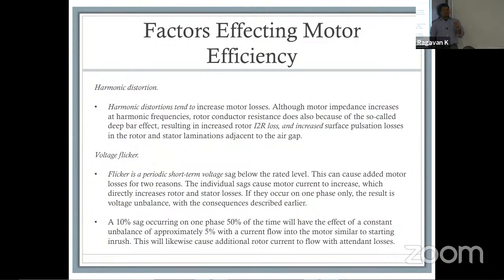Whenever you're designing a machine, in addition to all this, just keep in mind you also have to account for the wire, the cable that goes either from the inverter to the motor or from the supply. That inductance and resistance have to be accounted for in your controller, because the length of the wire has a contribution to play in what your drop in your winding is going to be.